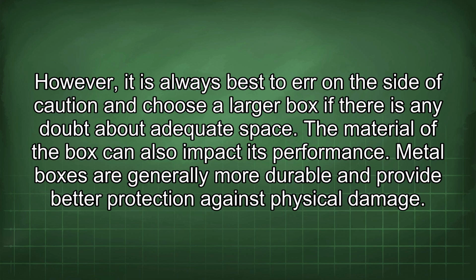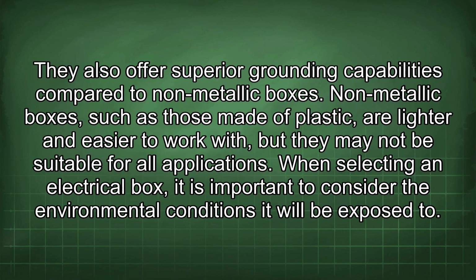The material of the box can also impact its performance. Metal boxes are generally more durable and provide better protection against physical damage. They also offer superior grounding capabilities compared to non-metallic boxes. Non-metallic boxes, such as those made of plastic, are lighter and easier to work with, but they may not be